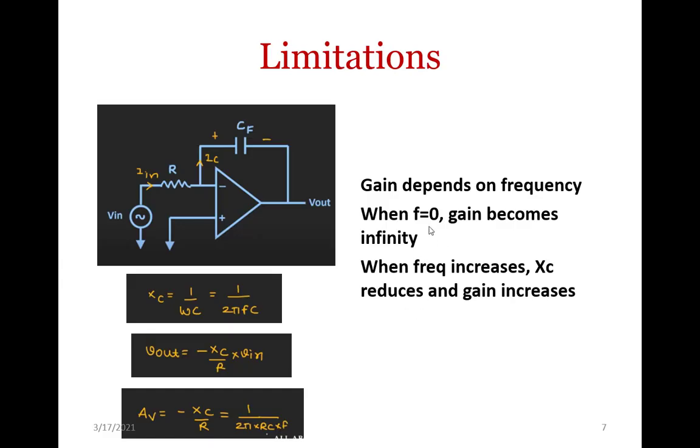Why is this happening? When f is equal to 0, the capacitive reactance Xc is given by the formula 1 by 2 pi Fc. So, when f becomes equal to 0, the capacitive reactance becomes infinite.